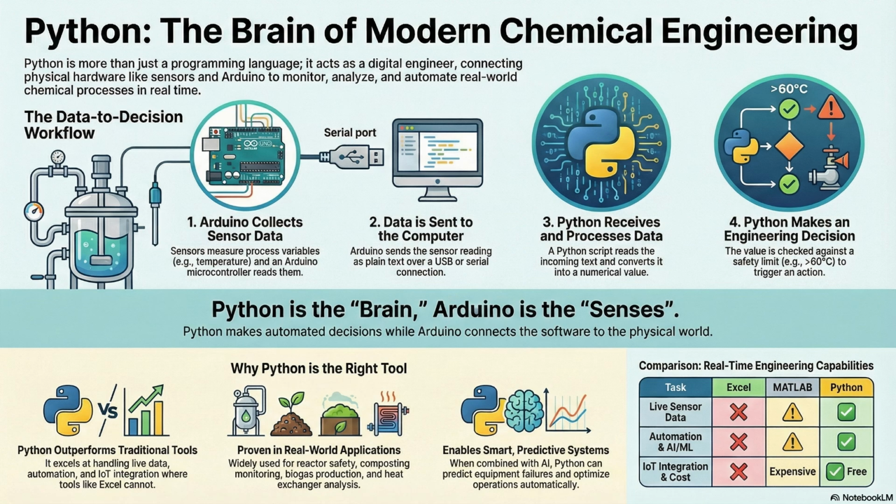And what about fluid flow? Well, you're moving liquids, so you need to monitor flow rate. It's critical for your mass balance. Flow meters like the YFS201 are pretty common. And then there are things like wastewater treatment or fermentation. Right, biological processes. In those cases, a precise pH probe is what keeps your system stable and active. Even in biogas systems, you're using gas sensors, MQ series sensors, to check for things like methane or CO.